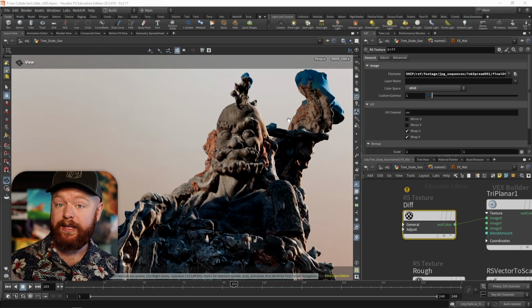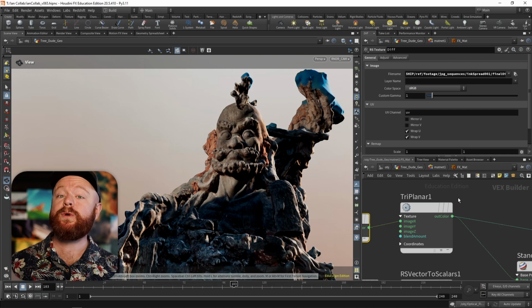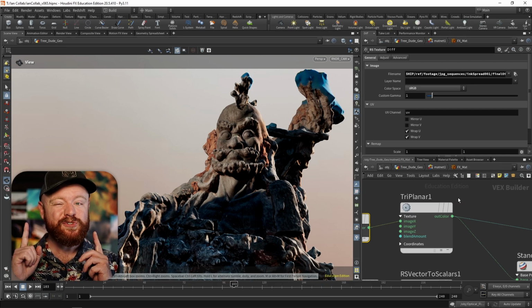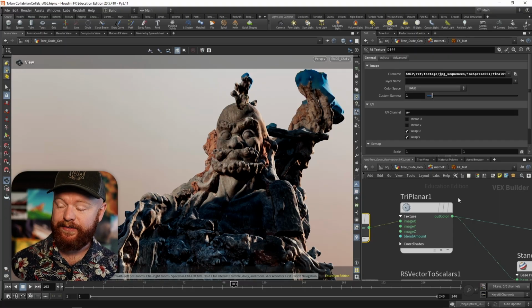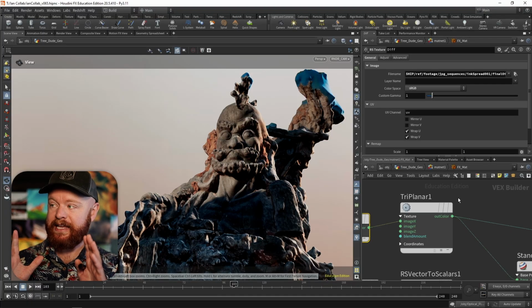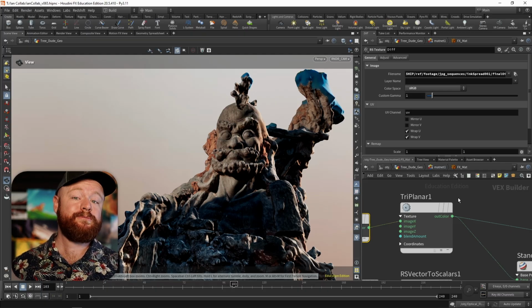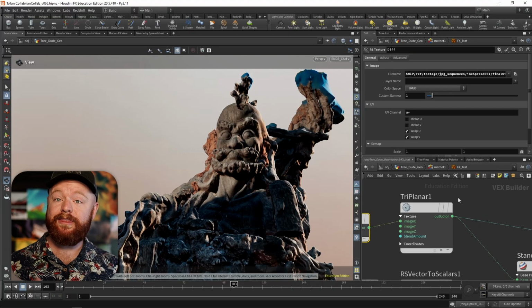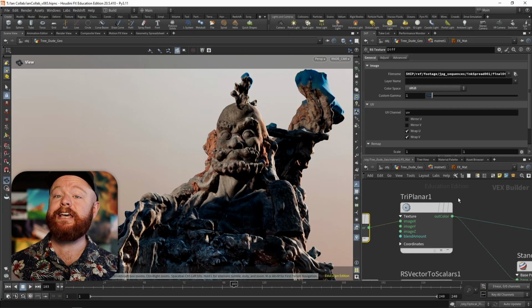But that ought to bring it into our texture node. It goes to triplanar, and then at render time, we see everything being applied to the model. There's just one problem though. We can't take that data as it is right now and make it work with Optical Flow. We need all of this to be in UV space so that we can flatten things out and utilize our 2D voxels. So in order to make that happen, now we need to bake this signal into a texture map.